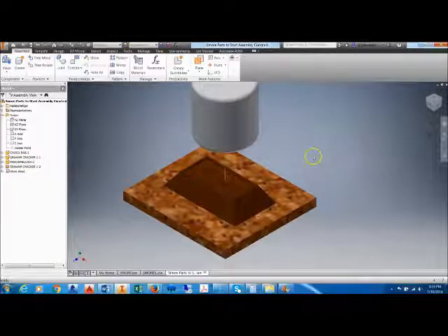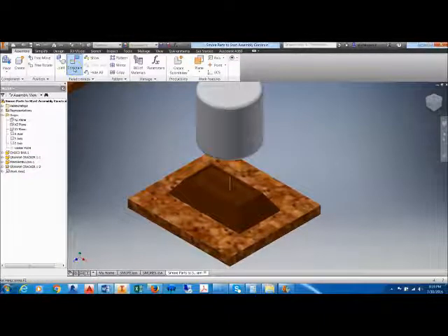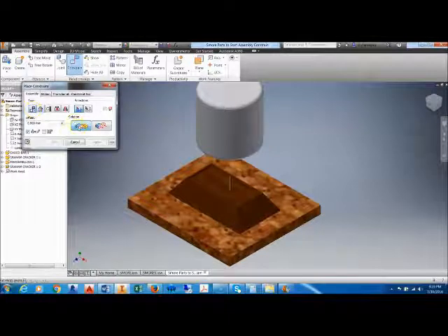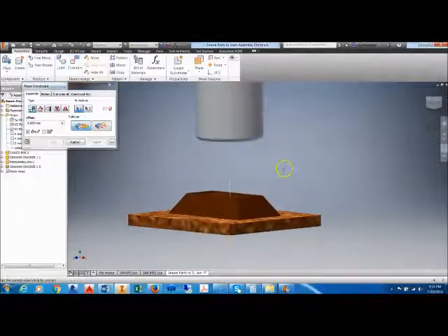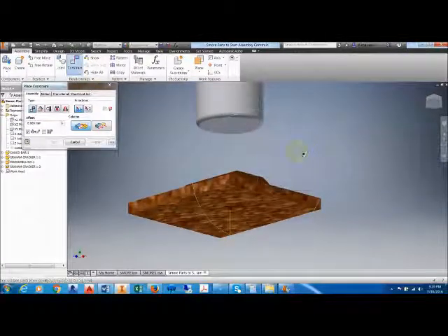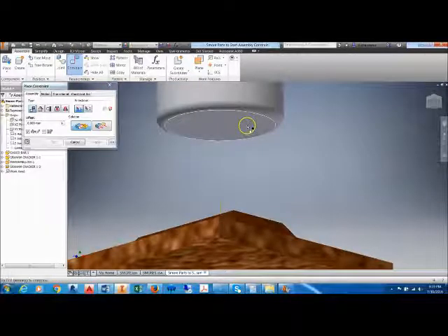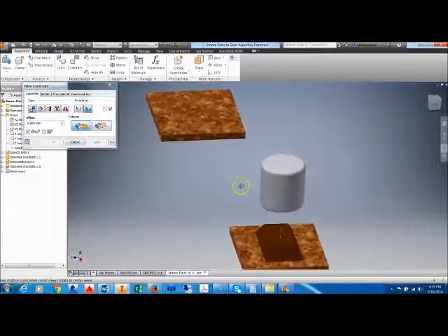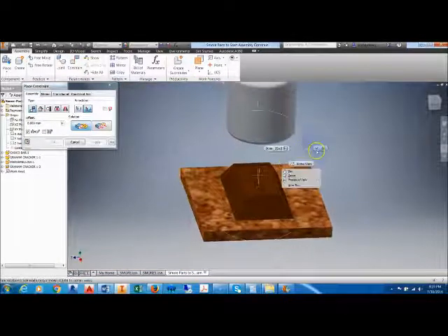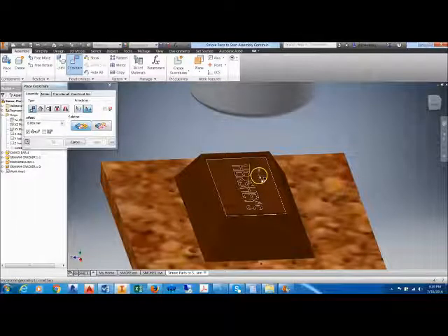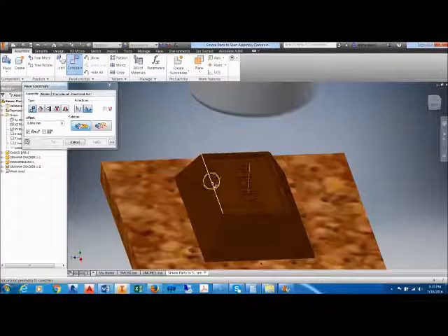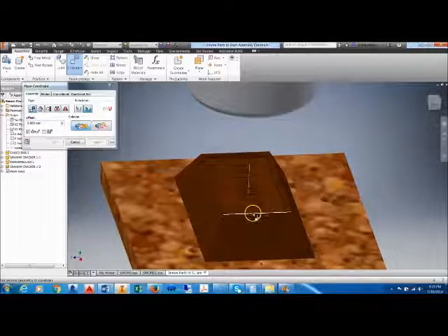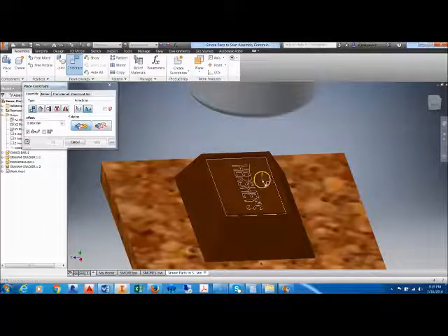Setting the height will happen in the same way, where we will grab the constraint tool again, and again it's going to be type mate, solution mate, and I'm going to then use my free orbit and rotate my entire assembly around so I can grab the bottom of the marshmallow, and it's the face of the marshmallow, and then I'm going to free orbit rotate back around till I can see the top of the chocolate. Now, I can select the indentation face, or I can select the top edge of one of the pieces of chocolate. I'm going to utilize the indentation face.